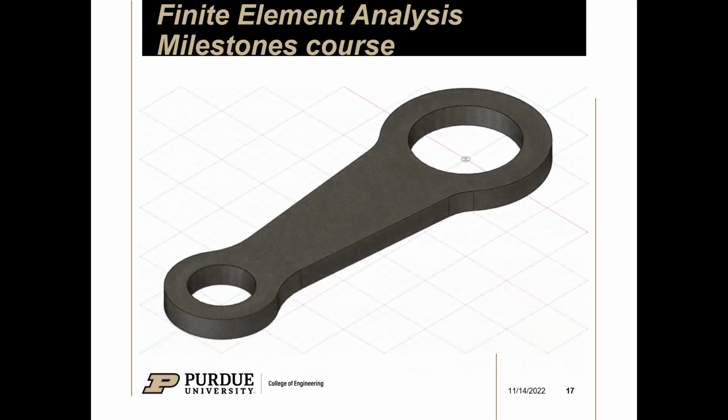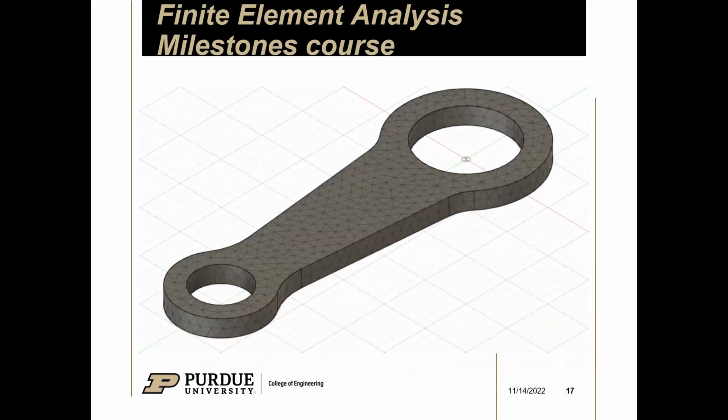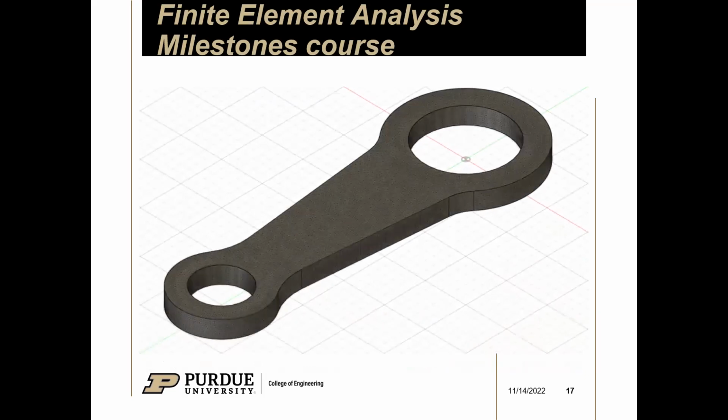As you can see, as the mesh gets smaller, our analysis actually gets more and more accurate, but it does come with a cost: the simulation will take very long to load, and oh boy, it gets bad, guys. Further along the course, we'll see how decreasing the mesh affects our results, and also the time it takes for our computers to run the simulations.